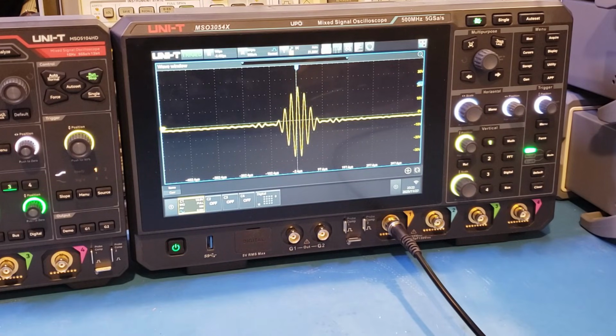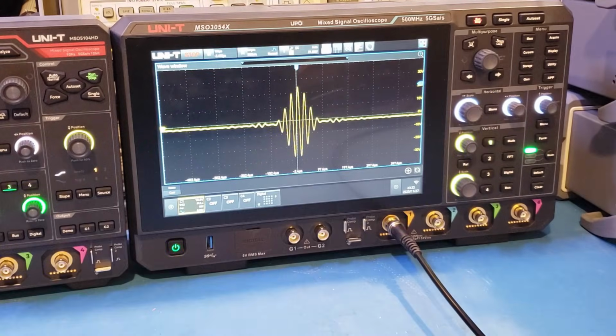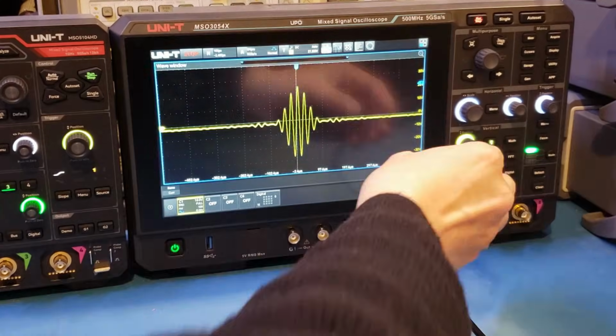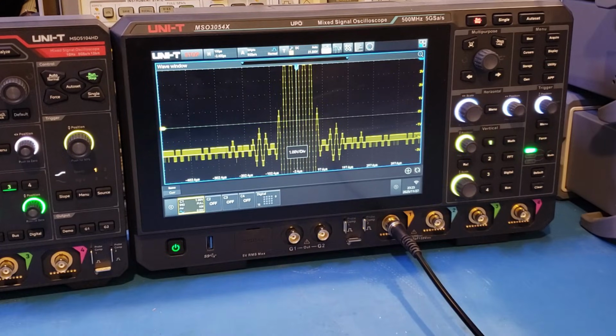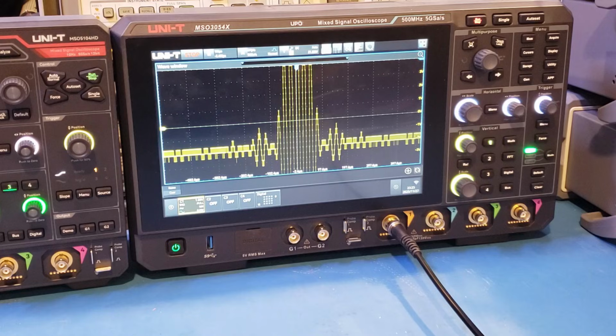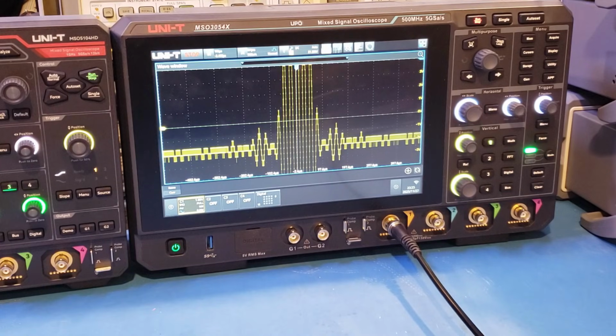So for this demonstration, I'm actually capturing signal on the 3054X. This is a wavelet signal, and you can see here we captured the stable signal. Anyway, so now let me pause the acquisition. And now let's actually adjust the vertical scale. So you can immediately see that the captured signal actually shows a lot of quantization errors. That's because we're capturing the signal using 8 bits.